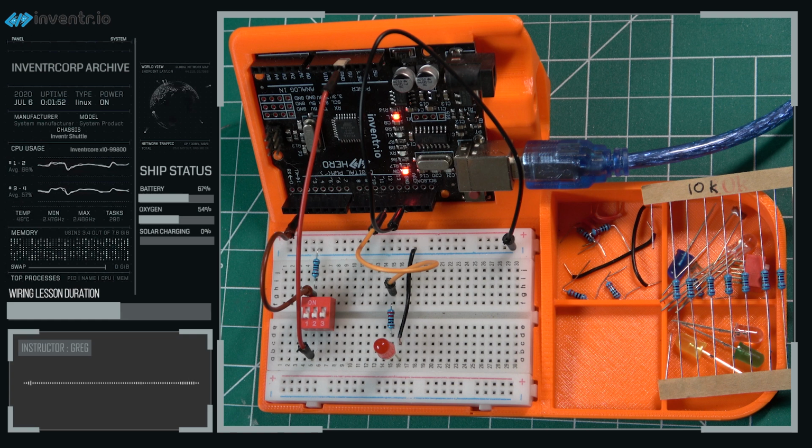There's just one last detail to mention here before we go ahead and test this new circuit. Because we have more than one current loop operating on our breadboard here, we have need for more than one set of supply and ground connections. And this is a situation that'll happen quite frequently. Rather than providing separate connections for our two loops, our two sub-circuits, we'll set up shared common lines or buses that can be tapped by any sub-circuit on the breadboard that needs to.